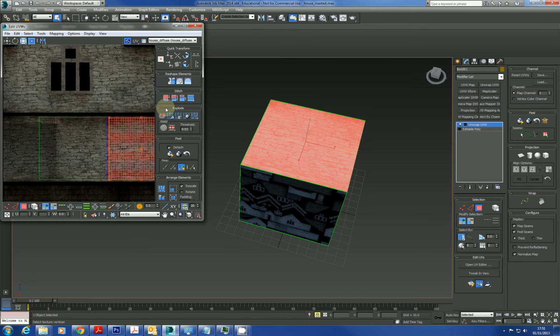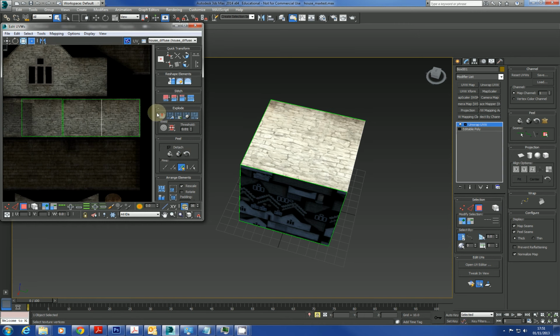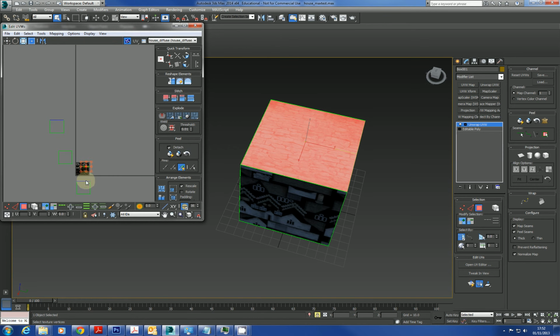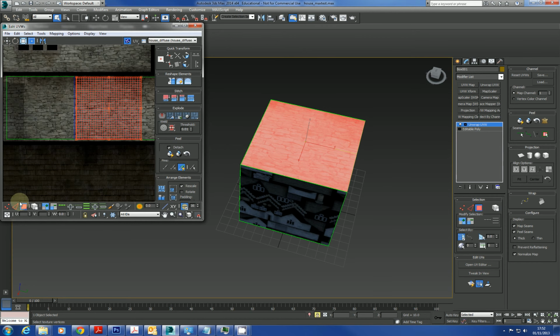In this case, you can even use this one now, and again, you can use the stitch custom. One second, I'm selecting the whole of the face. If you select the whole of the face and stitch it, it's going to stitch this side, that side. All the seams are going to be stitched. As you can see, this one joins up as well. So when you know the edge that you want to stitch up, you go into edge mode, select the edge and hit stitch, and that'll pretty much just do that one edge for you.